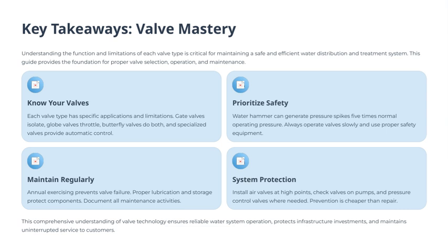Maintaining our system regularly is crucial because water hammer, for example, can create pressure spikes up to 5 times the normal operating pressure. To avoid damage, always operate valves slowly and make sure you're using the proper safety equipment. Safety should always come first.